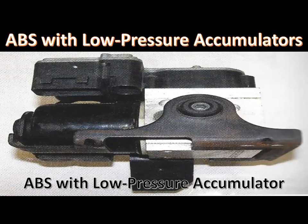Some vehicles have an ABS with the solenoid valves, low pressure accumulators, pressure pumps, and a control module designed into one unit. This type of ABS has a conventional vacuum brake booster to provide brake assist. The solenoids in this system are referred to as isolation and dump valves.